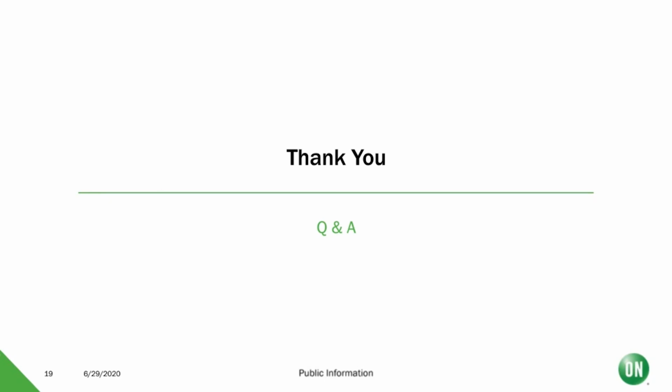Obviously, there are get messages, essentially "get me the temperature." There's an inbuilt mechanism where, if I sent a read temperature message and haven't received a response in a certain amount of time, I retransmit it. So there is an inbuilt acknowledgement baked into those. But if you really want to make sure that even a set message, where you're saying "set the thermostat to this level," is received, you would use what's called an acknowledged message.